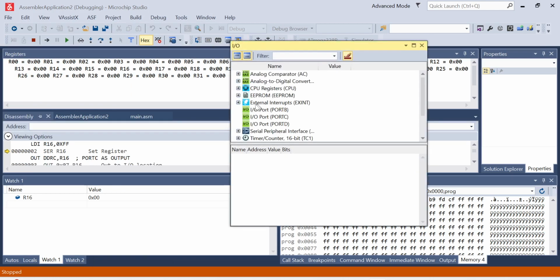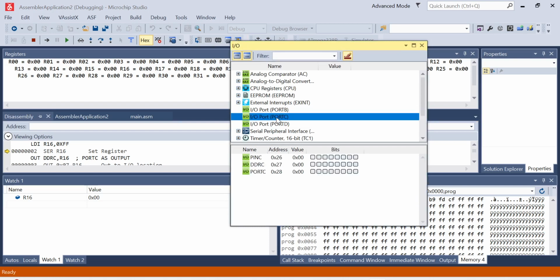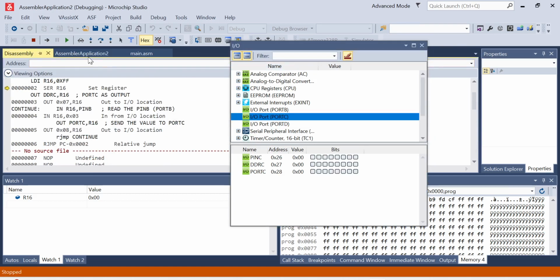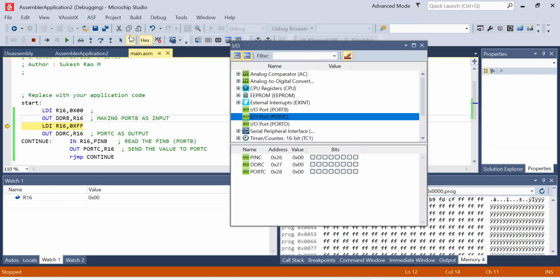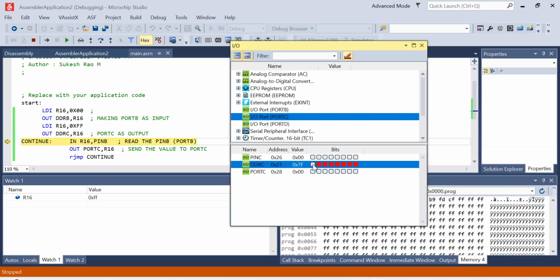Yeah, it's here. So in the IO register, you have port B here, port C here. Now, if you look carefully here, let me take you to this. Okay, here, done. So let me see how it is changing. DDRC, you see here the value will change now. I made FF here, port C value, and DDRC should be 7F, and why it is not taking, probably it is only the one port. Let me check it.